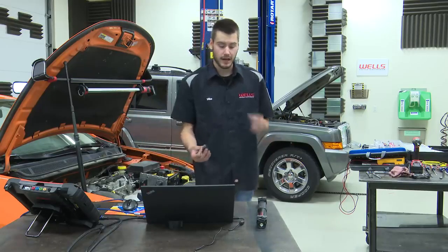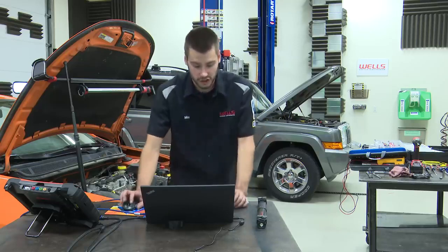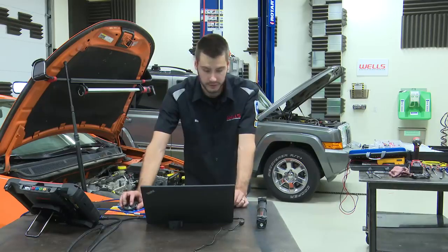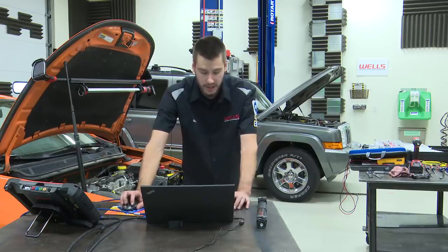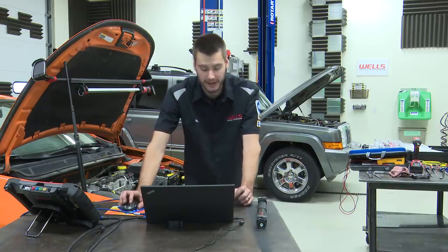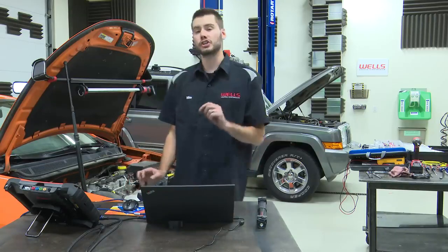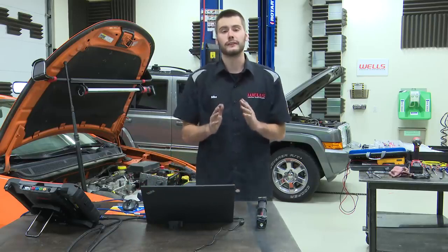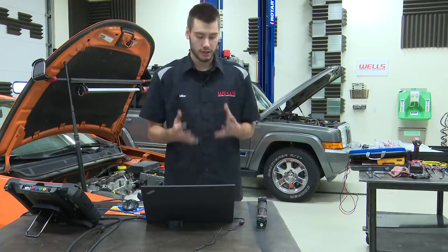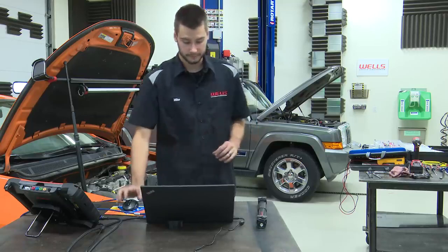Just so you guys know, on a Jeep, yes, you could use min-max potentially if it's fast enough. But on a Jeep, this will set a code, a P0124, if you have a 5-degree change in under 7 milliseconds. 7 milliseconds at a time, if it notices more than a 5-degree change, it flags a P0124.